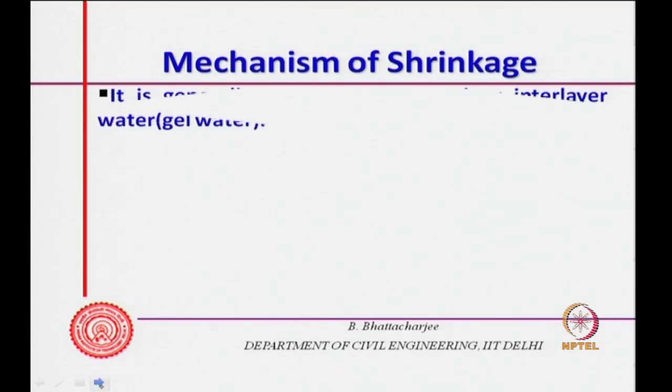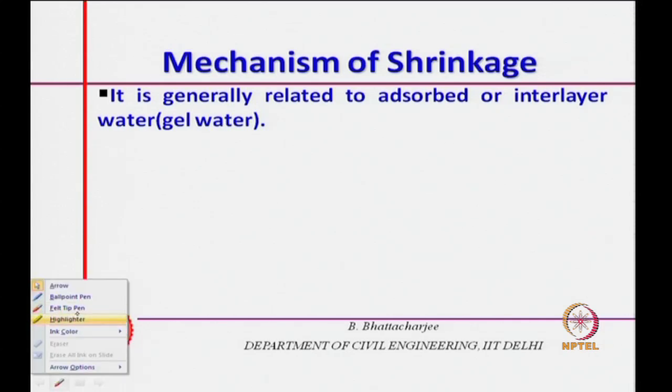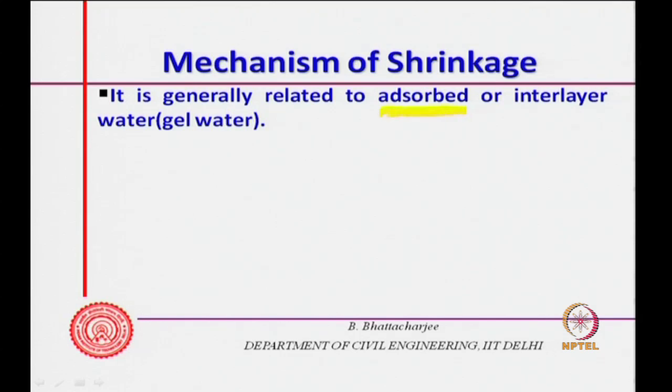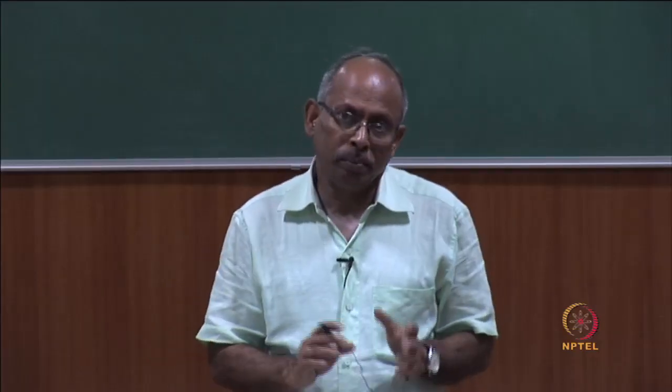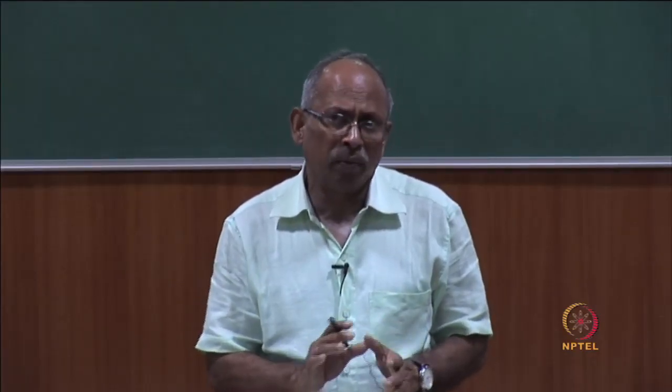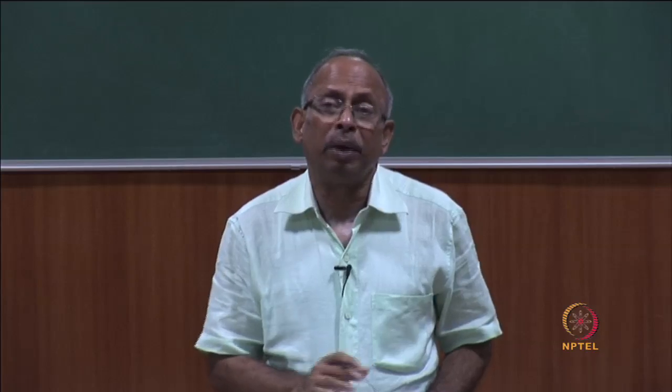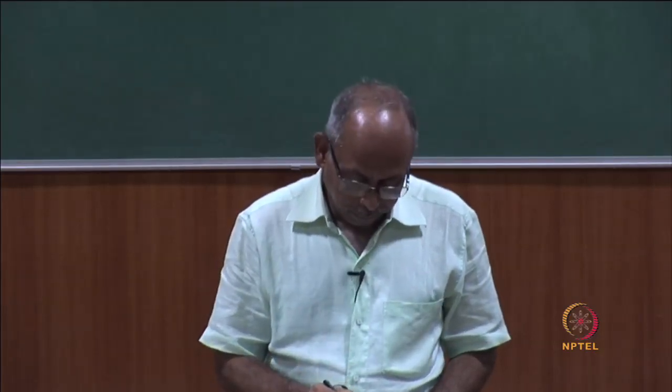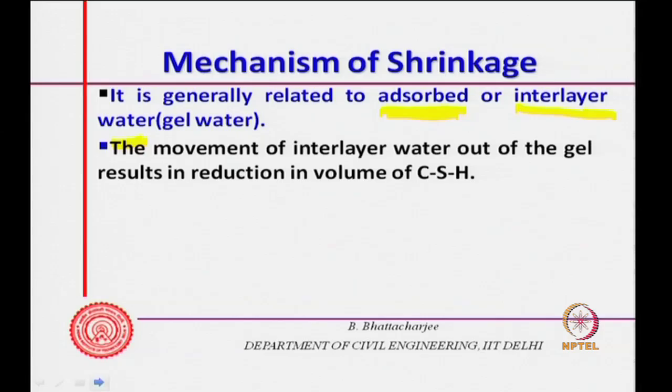So, mechanism of shrinkage. Like creep, it is generally related to adsorbed or interlayer water. That is why they are usually dealt with together, shrinkage and creep, and they have a similar sort of mechanism with respect to the microstructure of concrete. So, this is related to adsorbed or interlayer water.